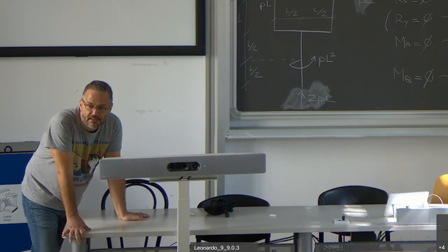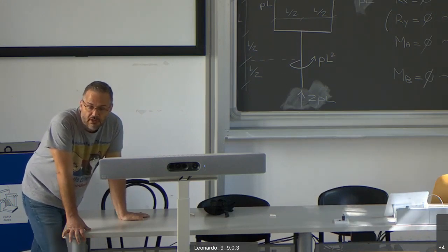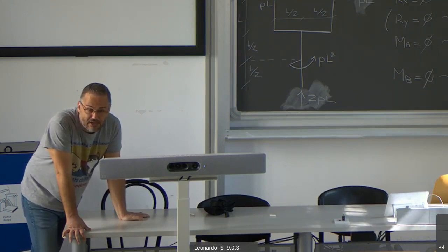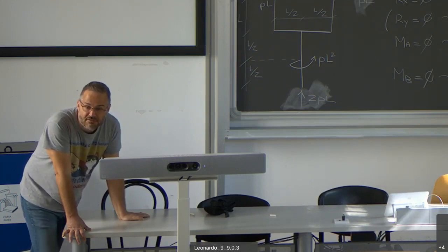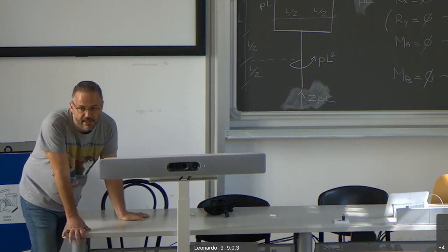As we always did, when I plotted the internal forces, I always made it clear whether axial force was positive compression or tension, whether the shear force was positive clockwise or counterclockwise. As for the bending moment, the way we plotted bending moment diagrams is to specify whether it is plotted on the tension side or on the compression side.